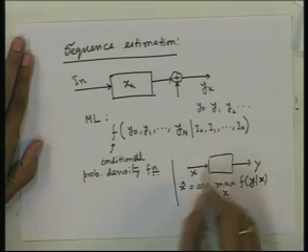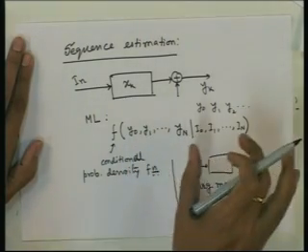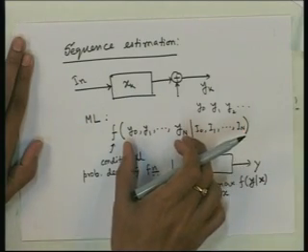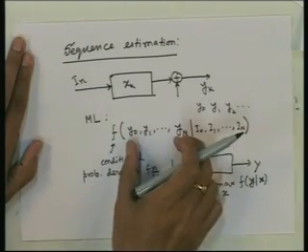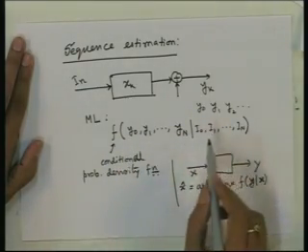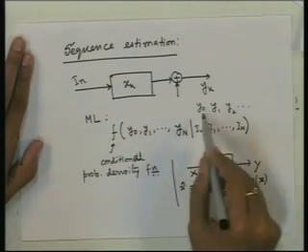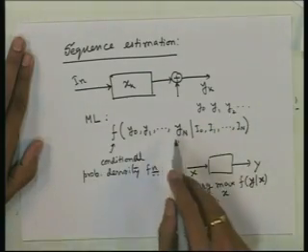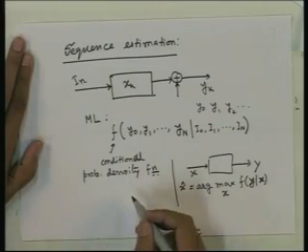So, that same concept is used here in terms of sequence. Say we transmitted one n length sequence and we have received one n length sequence, and we want to have the ML estimate of the transmitted sequence from the received sequence. So, we are saying our ML estimate is that transmitted sequence for which the conditional density function of this sequence given that transmitted sequence is maximum. That is the maximum likelihood estimate.